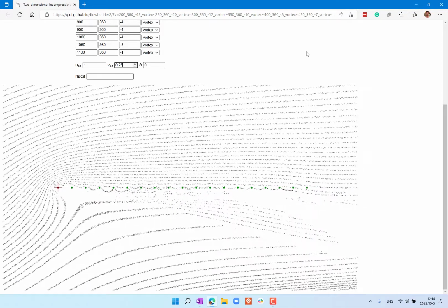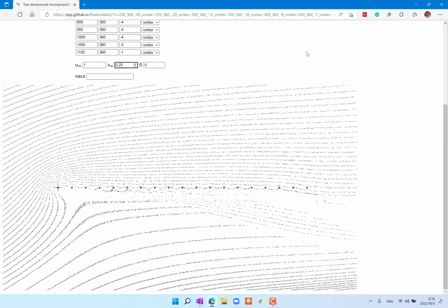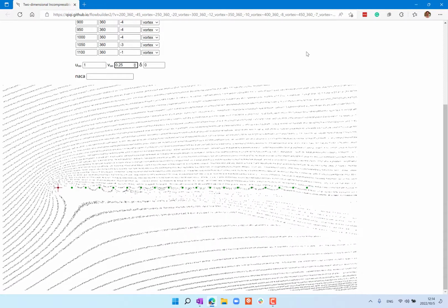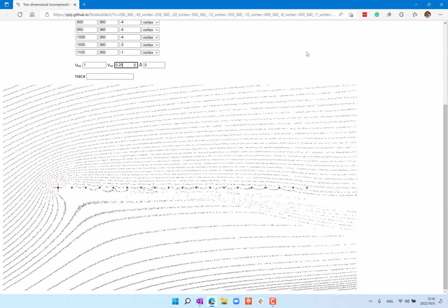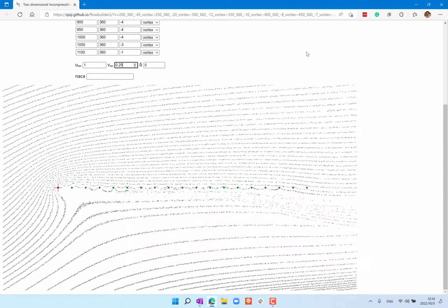The other completely equivalent thing to do is to rotate the world and keep the airplane exactly the same. That is basically changing the free stream velocity to have an angle that points upward. That's completely equivalent to rotating the airplane to a higher angle of attack. You're just rotating the frame of reference. In a wind tunnel, of course, it's much easier to rotate the model than to rotate the whole wind tunnel.